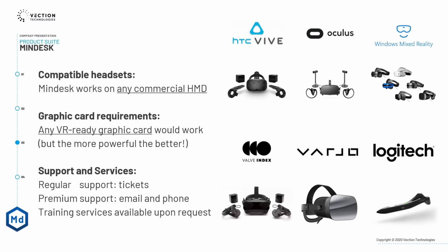Also, in terms of graphic cards, pretty much any graphic card is good as long as it's VR ready, which means professional VR graphic cards from the last 3 years should be good. If you have a Quadro, probably you're fine. Just make sure that the Quadro model that you have is on the VR Ready list on the NVIDIA website. And also, if you have a GTX, anything from the 1060 and beyond should be all right.